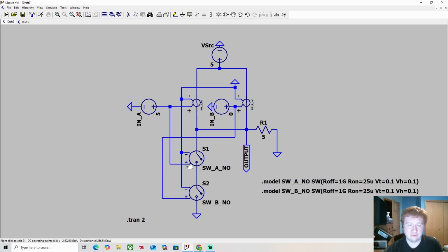This switch right here would now turn on, meaning that it closes, so you would have current going from here to here. But since the other voltage is 0, this switch stays closed, so 5 volts comes through and current is allowed to pass through this switch, through the resistor, still having 5 volts. But since this switch is closed, but this switch is open because of 0 volts to the other switch, there's no path to ground here, so it can't be 0 volts, it has to be 5 volts. So that's 0, 0, 0, 1.